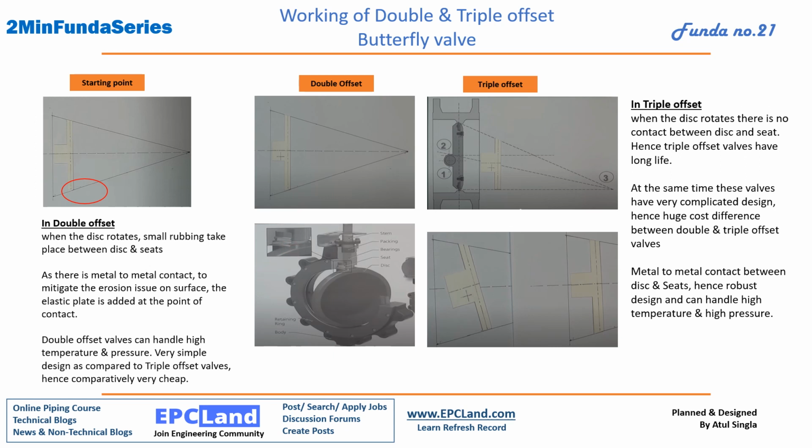What is happening in triple offset? We have shifted this point to a third offset. Now the disc rotates keeping this point as the center, and there is no touch at all with the seat. So this is a very safe design, there is no metal to metal contact and no chance of damage. This is a typical configuration of a triple offset valve. This is a straight configuration, and if we shift the shaft center line to this point along with an angle, this becomes the third offset. So in the third offset there is no contact between disc and seat.